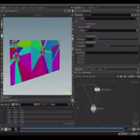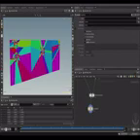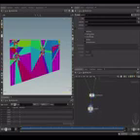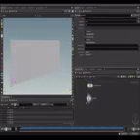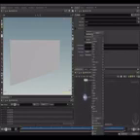So let's assemble back these pieces. We don't need a name attribute because it's coming from the Voronoi fracture sub. So turn this off and turn this on. And you should save this to disk at this point, but I'm going to use a stash node instead.